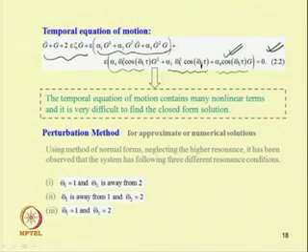So, we can have the instability region. Here it may be noted that due to the base excitation we have a nonlinear parametric term, that is the coefficient of g square equal to alpha 4 omega 1 square cos omega 1 tau, but due to the axial loading we have the term alpha 6 cos omega 2 bar tau into g. So, this alpha 6 cos omega 2 tau is the coefficient of time modulation of g. So, this is a linear parametric term, but the other term is the nonlinear parametric term.